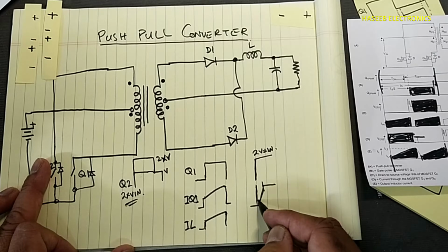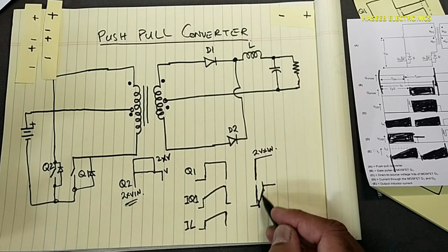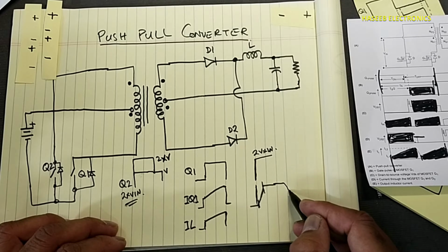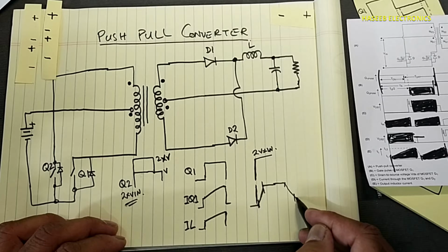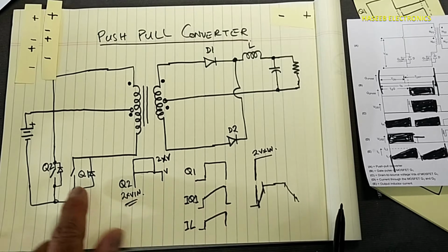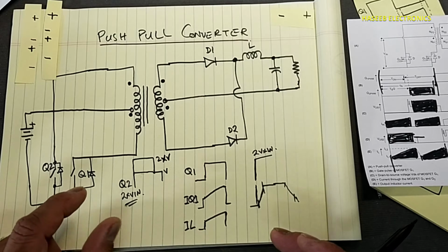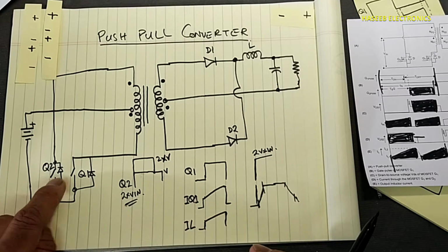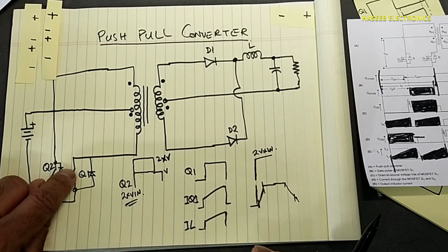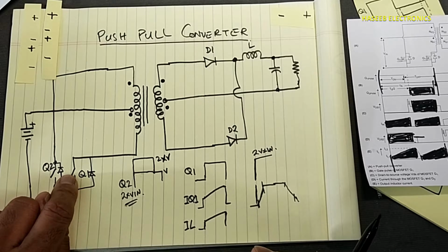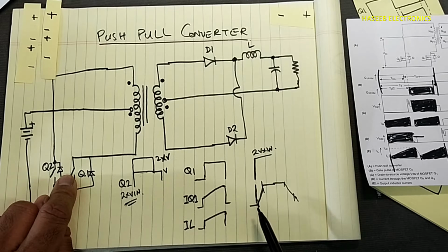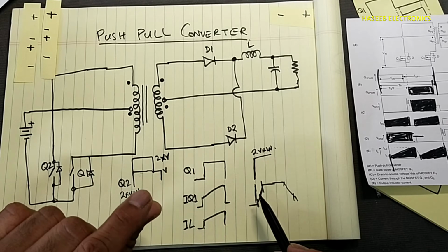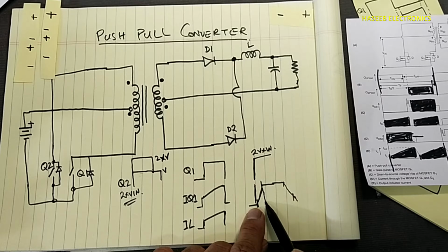So in this portion, in the rising edge and also in the falling edge, its channel resistance will vary from high to low or from low to high. When it is turning on, before turning on its resistance was very high. Now when it is turning on, it will not turn on immediately, so its resistance will change in this time.